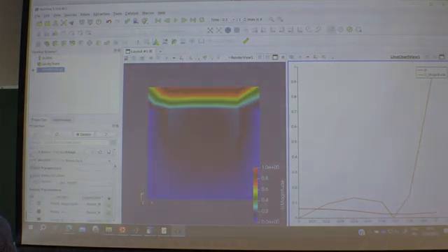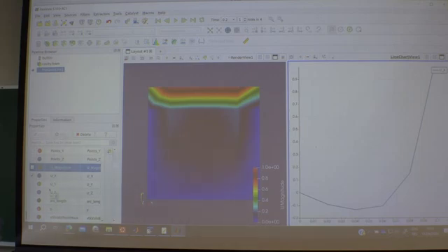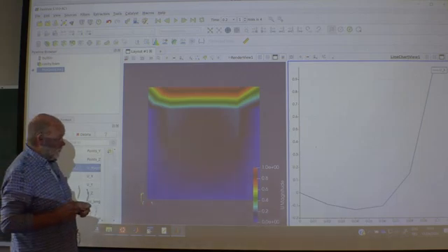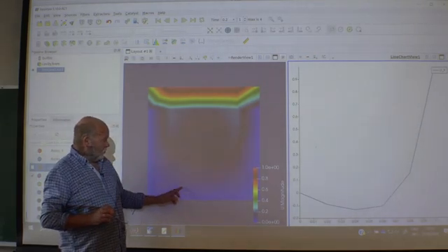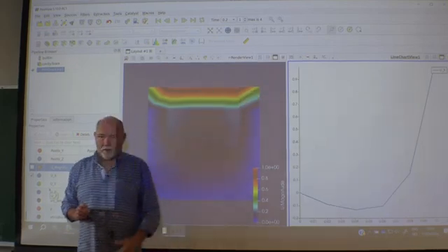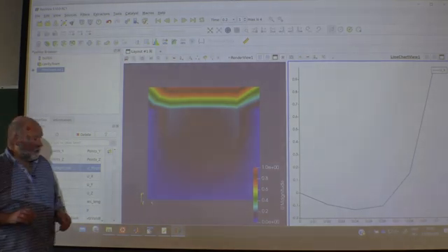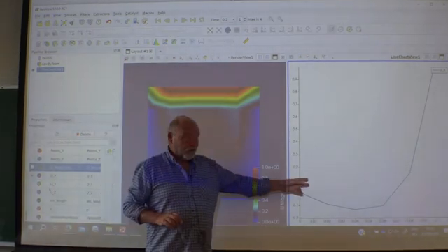And if you look at what you plot, you get U magnitude by default. I don't want that. I want U. Away with that one. And also, I don't need the pressure here. That's all important. I want that one. There you have the velocity profile. Starts with 0, goes negative, and then big 1 at the top, of course. So not so stupid. I want the data for this curve.